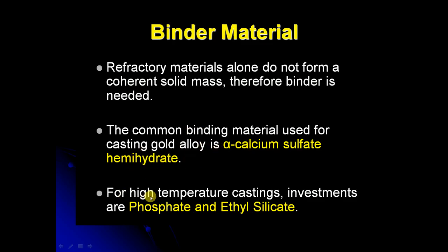Important: for high temperature casting, the investments are phosphate and ethyl silicate, as I have already told you in the definition. For lower temperature casting the investment is gypsum.